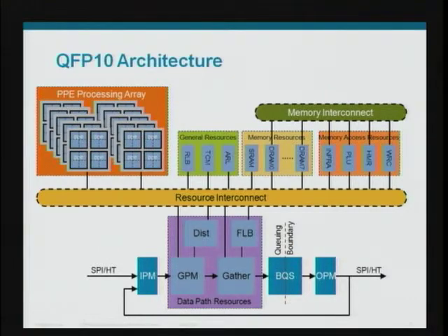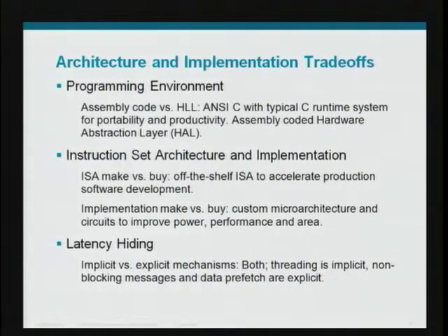The other key points from a memory standpoint, we're using RLDRAM2 technology. We do have TCAM interfaces. The total memory bandwidth across all of the queuing, scheduling, and all of the resource DRAM comes to, I think it was 400 to 500 gigabits kind of range, so 60 gigabytes kind of area of total memory bandwidth.